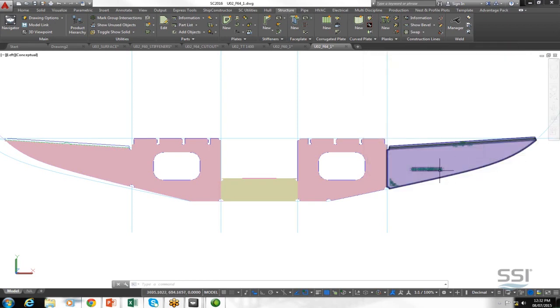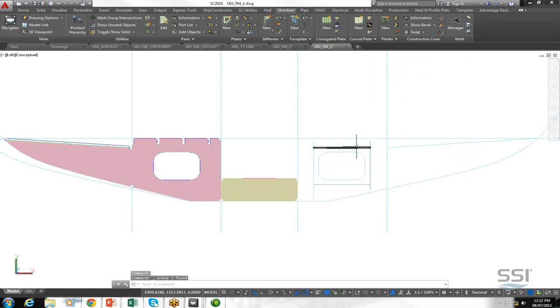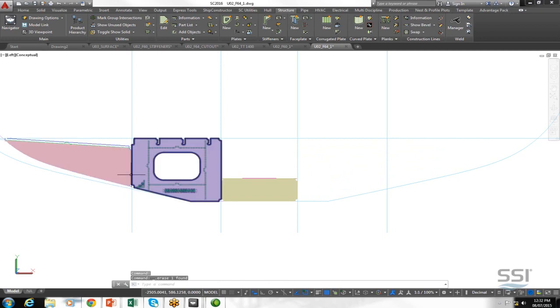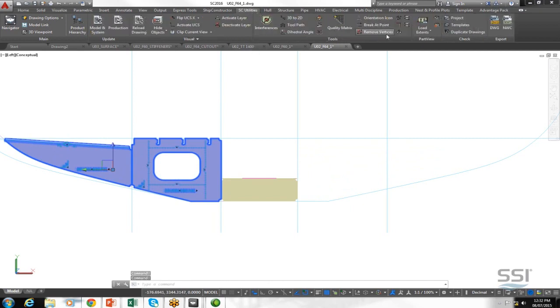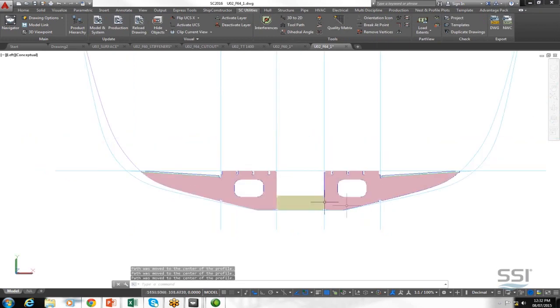So to simulate that this time, we're actually just going to delete our frame 64 counterparts and the construction lines that went along with it. And we're going to simulate the replicate first and then mirror behavior. So we're going to mirror these parts across to the other side. So now we can see we have our parts with our new hull shape definition exactly as we want.